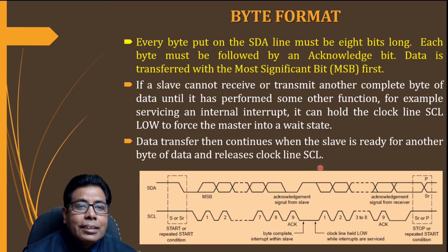So every byte put on the SDA line must be 8 bits long, and it is followed by an acknowledge bit. Data is transferred with the most significant bit first. So the MSB is transferred first, and then the other bits will be transferred, with the LSB last.